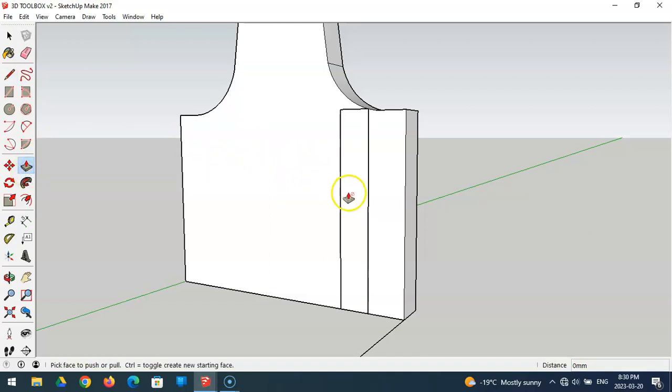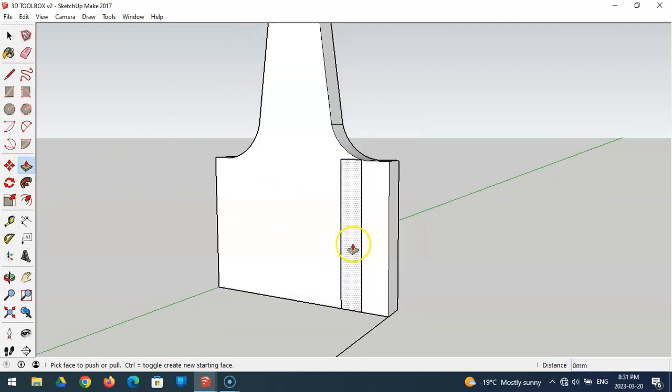Now this rectangle, let's see here. Oh, it's grouped. Because it's grouped, I don't think I can push-pull it unless I drew the bottom. So let's try drawing the bottom. And now let's maybe try, yep, there. Now it's a complete rectangle. Now I can grab it by single-clicking with the push-pull tool.